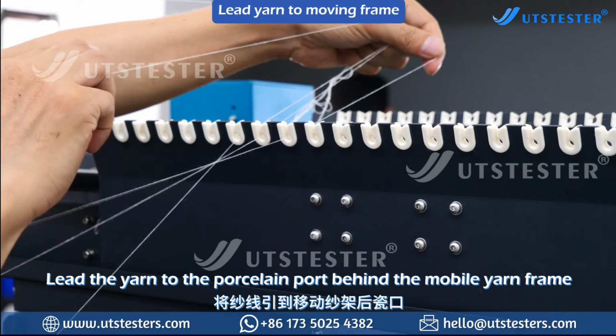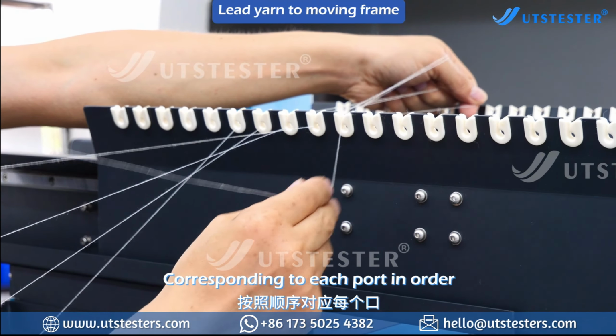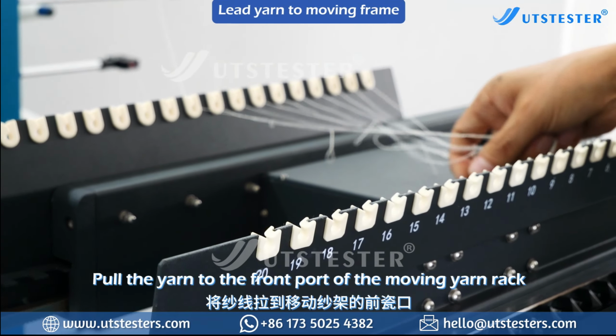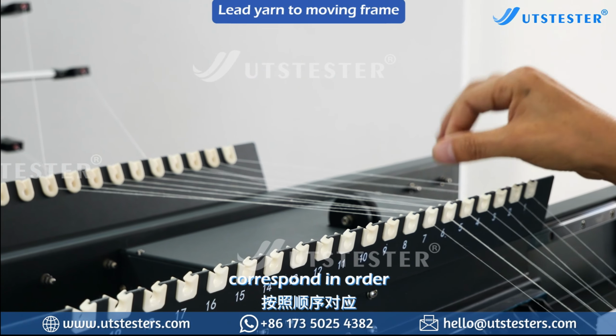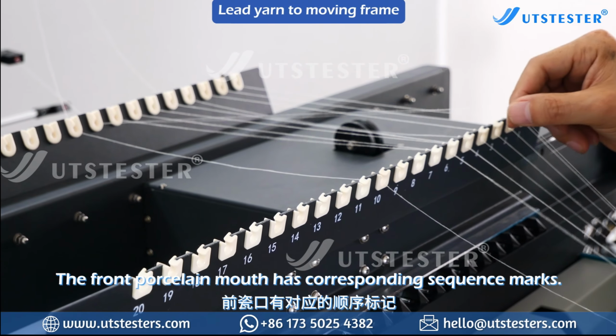Lead the yarn to the porcelain port behind the mobile yarn frame, corresponding to each port in order. Pull the yarn to the front port of the moving yarn rack, corresponding in order. The front porcelain mouth has corresponding sequence marks.